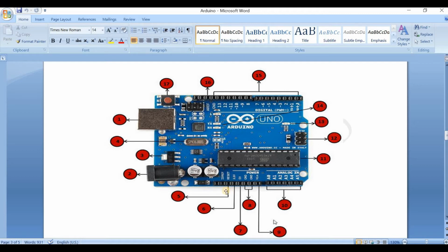Next, this is the reset pin. By using this pin, we can reset the program in the microcontroller. It means the execution of the program starts from the initial position. Be careful while giving the voltage to this pin to reset, and refer to the datasheet before doing it. According to a study, the voltage to be given to the reset should not be more than 3.6 volts.